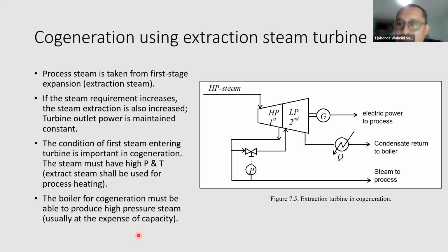When you want to execute a project, when you want to build a plant, you also have to look for what's available in the market. That is when our creativity as engineers must be toned down. Let's say that your fluid flow calculation calls for an ideal pipe diameter of, let's say, 11.5 centimeters. And when you look for that kind of pipe in the market, you don't find any. What you find are 10 centimeters and 11 centimeters. So now you have to decide which one to choose, because clearly custom ordering pipe just for a chemical process plant doesn't make any sense at all. So again, you have to adjust yourself to whatever's available in the market.